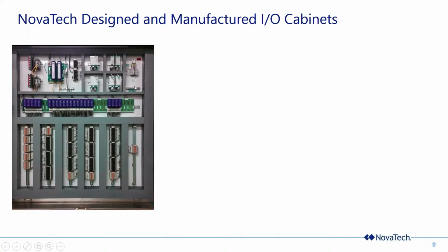Power comes in, 120 volt power or 220 volt power, into the cabinet at the right here, and from that point it goes to redundant 12 or redundant 24 volt power supplies. They go out through circuit breakers, they power the eBIMs, they power the network switches, and the only place you have AC is up in this corner unless you have AC field wiring.